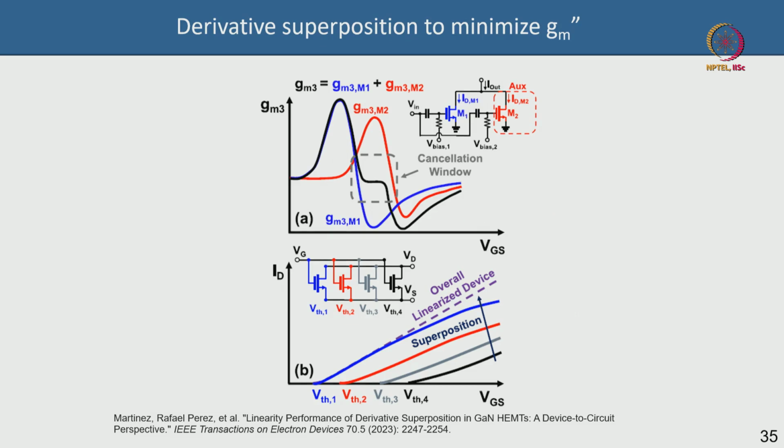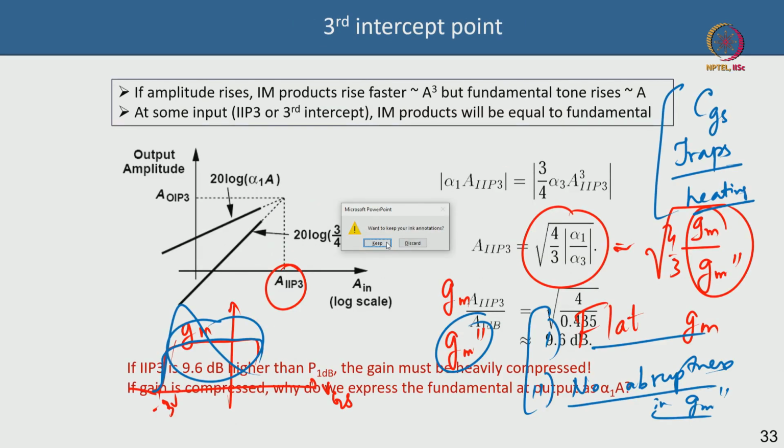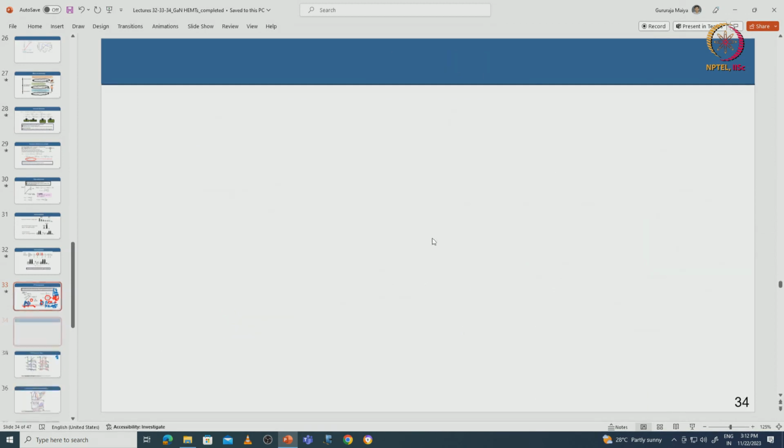So before I go to this, maybe I have to take a small detour here, because I want to say what it means to have a system. Linearity is very important in RF power amplifiers for wireless communication, maybe 5G, etc. Non-linearity can significantly distort and corrupt your signal. So although you are going to increase the efficiency for better battery performance and longer battery lifetime, it is not like you can sacrifice all linearity. Linearity is very important for better signal integrity and fidelity.